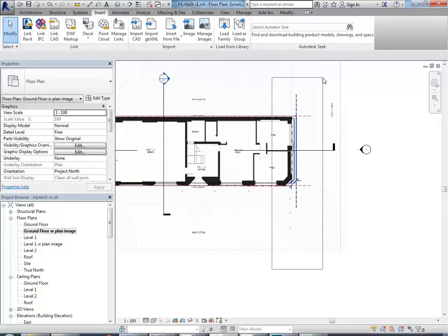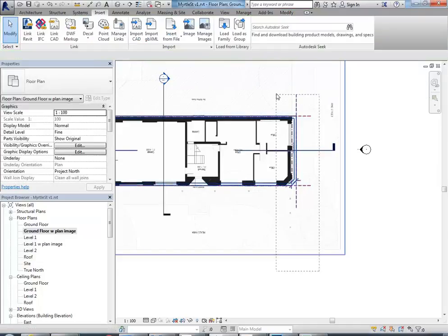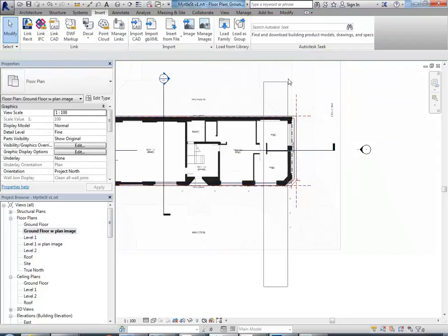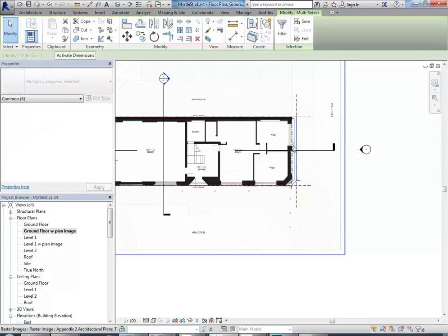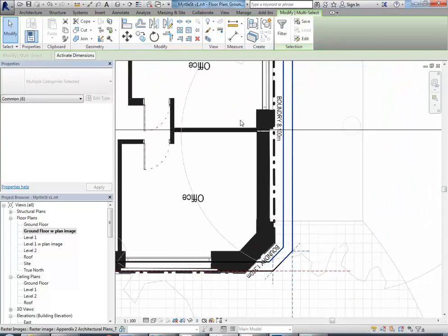So if you had a look at this in AutoCAD, windows versus crossings, left to right versus right to left. If I go right to left, it will select everything inside the window and everything that window's touching, which will be too much. So I just want to go left to right and just get the things inside my window. So it's really important you just have those fundamental selection tools down when you're doing things like this.